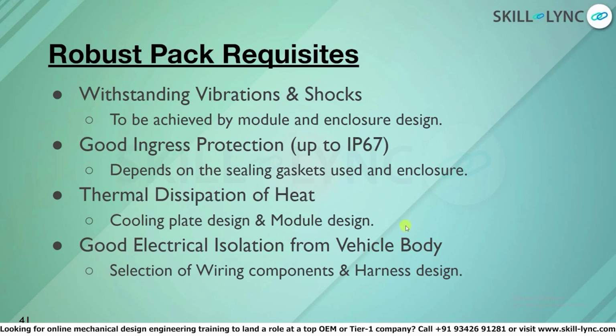When we need to do this test for transportation, like if we are shifting the pack from one place to another, there is a standard called UN 38.3, and that calls for vibration levels up to 5G or 8G. So imagine what kind of engineering you need to put in so that the module and the whole pack will sustain such vibrations.